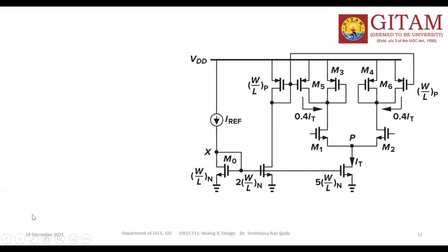Yes, sir. So this current I am giving is the biasing for this current source and this current source, similarly for this current source. Sometimes you should forget about the type of transistor, the ratios, all the things. Just the basic is: we need biasing for the PMOS loads as well as the NMOS tail current source.